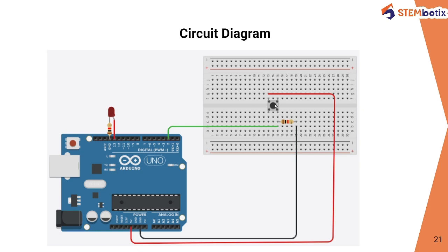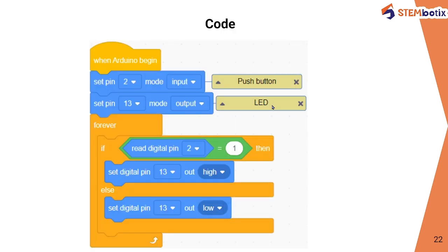because whenever you are pressing the push button you are giving it a signal that yes, the push button is pressed. Now it's time for the LED to turn on. This is how the push button or switch works: when you press that particular switch or button, the device connected to that particular push button or switch should turn on. So this is the input device, and in response to this release or press the device works, means the device turns on or turns off. Hence this is the output device. So onto pin number 2 the push button is connected and that push button is input.